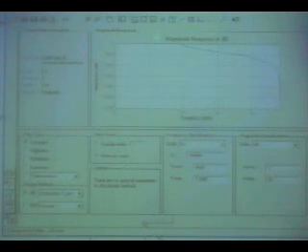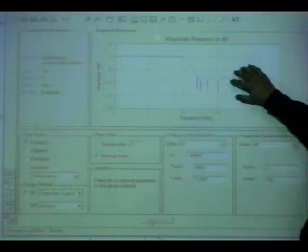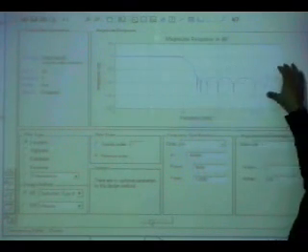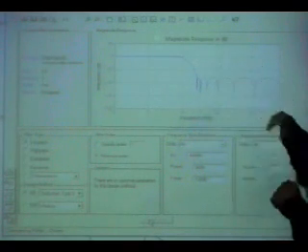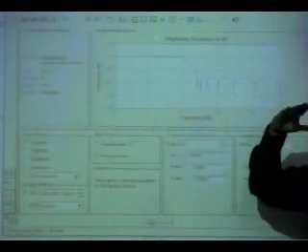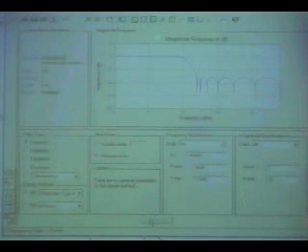You say, what if I say Chebyshev type 2? And you say design. It says a type 2. Remember, you see ripples here, because in dB these ripples are more pronounced. It's more significantly seen visually because of the dB, but as you can see it is at minus 80, it will never go above minus 80 dB, because that's what you said, minus 80 dB, 0.0001, right?